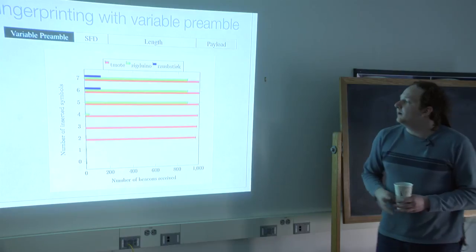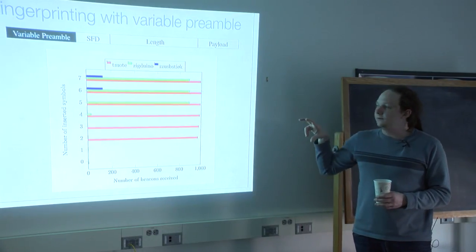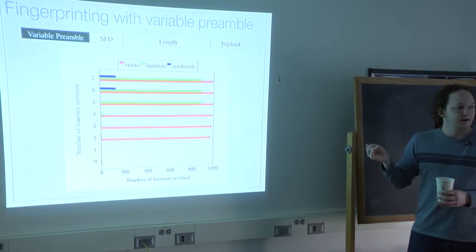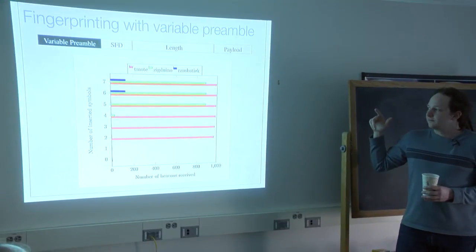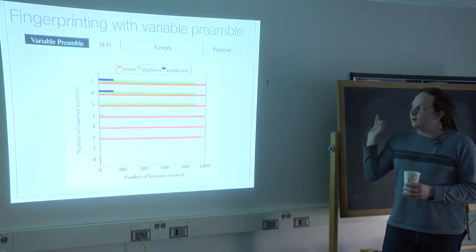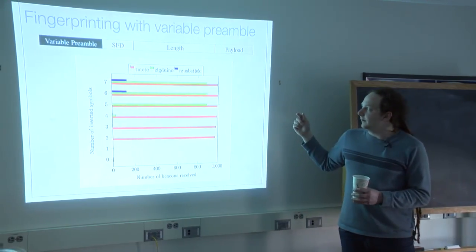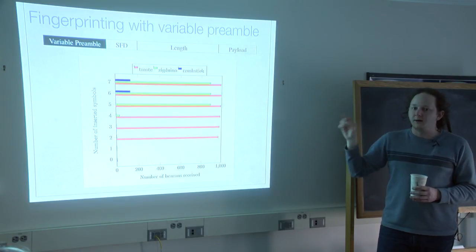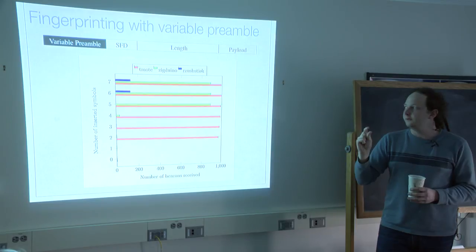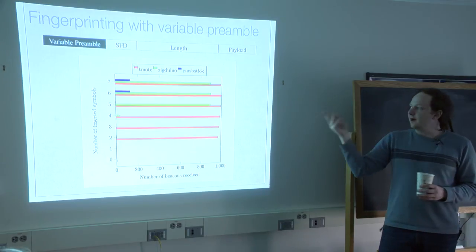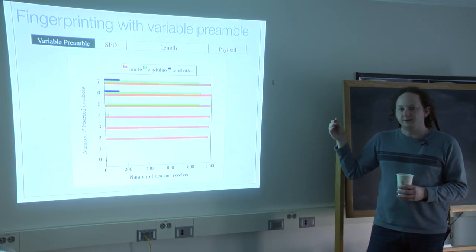So by changing the number of preambles that we sent, we were able to selectively transmit to only certain devices, in order to transmit just to the T-Mote or just to the T-Mote and the Zigduino while cutting out the RZ USB stick. And these use 3 different radio chips. The T-Mote uses the ChipCon 2420. The Zigduino uses an older Atmel standalone radio chip. And the RZ USB stick uses a more modern Atmel chip. And you can see that these have drastically different tolerances for a shortened preamble.